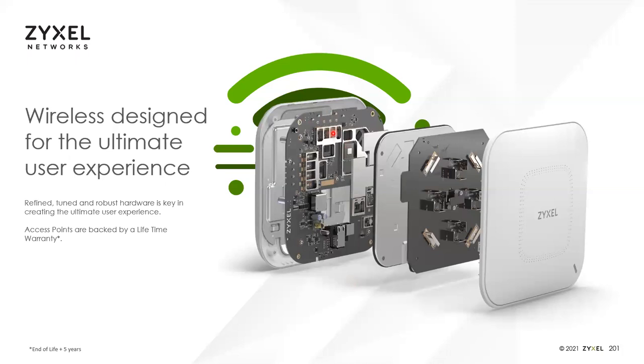Another thing you will notice on here is you will see a lot more shielding on the board than you will see on our competitors' products. So not only do we provide the standard shielding around the Wi-Fi devices, we provide additional shielding to help block EMI, but also to filter out 4G and 5G. These can be in very neighboring bands to our 5 gigahertz and 2.4 gigahertz and can cause interference and overlap. So we've put additional shielding on there to help block out that 4G and 5G interference.